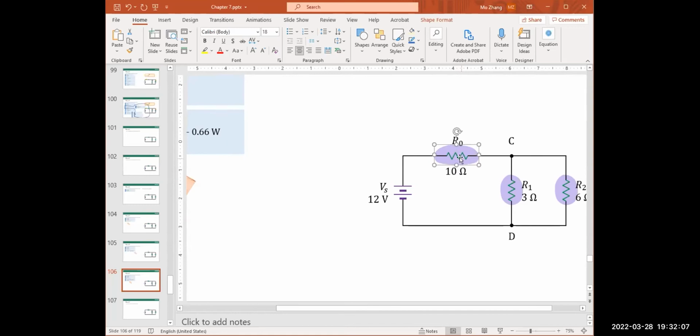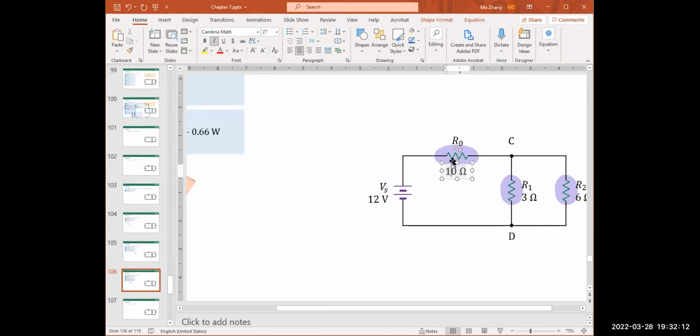If we choose a resistor that's 10 ohm, however, it cannot handle 10 watts, this resistor will be barbecued, will be toasted, will be burned out. And then you see first the smoke come out, and then you smell this bad burning smell. And then perhaps some sparks fly around, and then at the end, the circuit is not working. It's burned, it's a big hole in the wire.